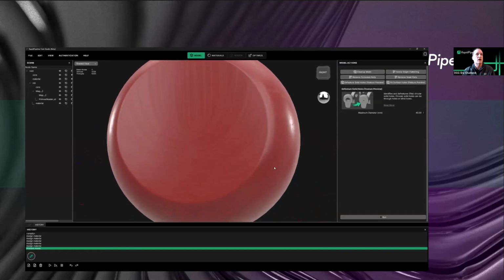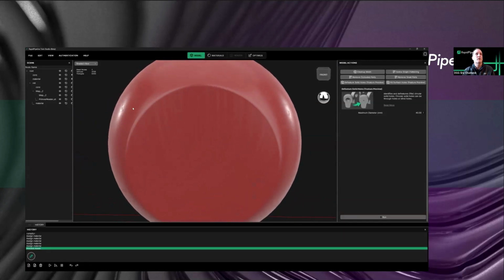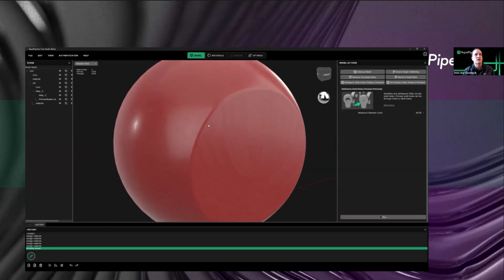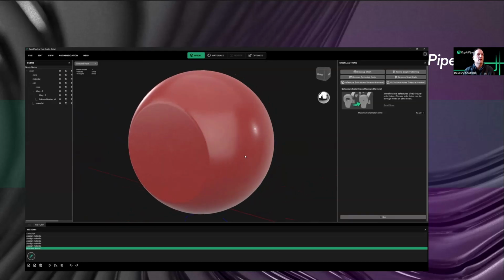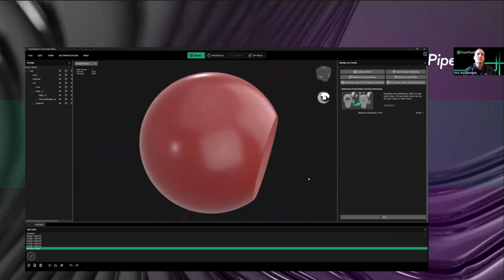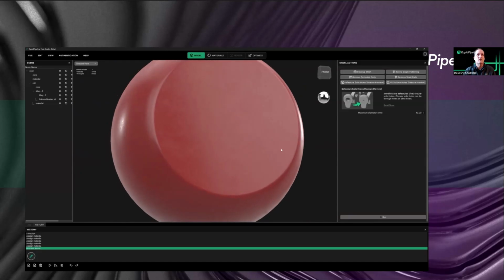Now, what it does is it tries to anticipate what the UVs should be for that surface, but it's trying to interpolate new UVs across the filled surface from the edges. That's where it's maybe not the best solution, but we can automatically fix that again by just doing an organic atlas. And now we've got great UVs across that surface again. And what's cool is that it's actually smoothed that surface across.